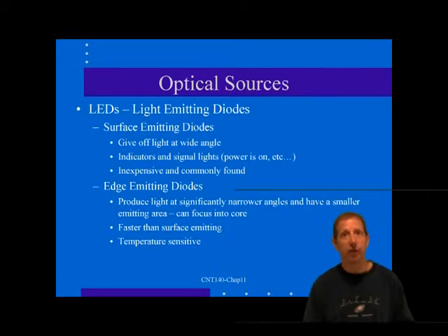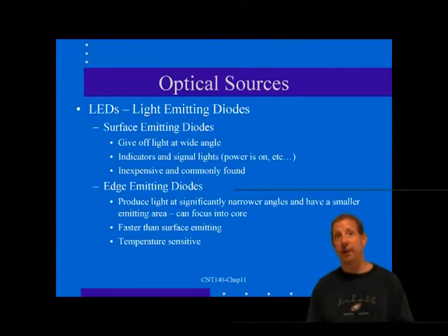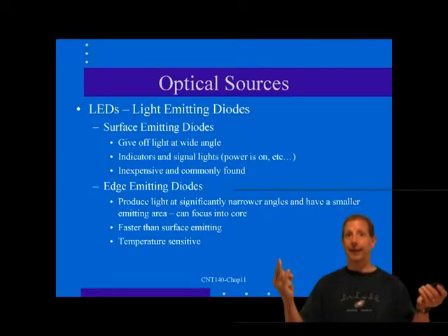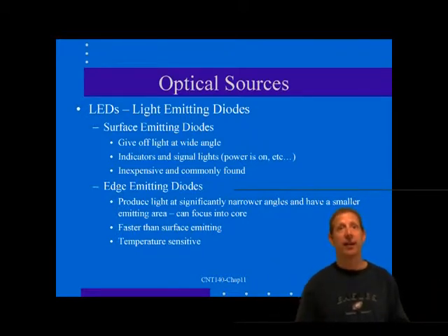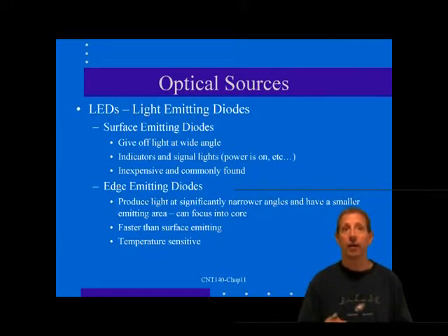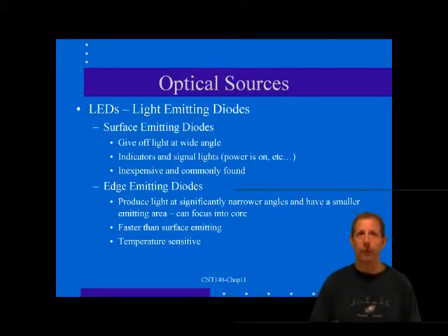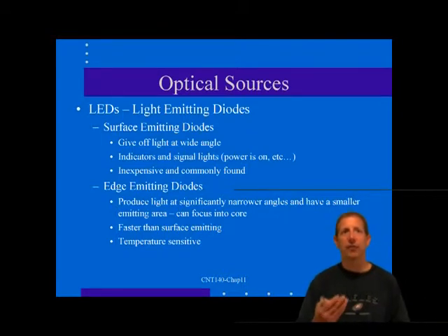However, as we just covered, much of the installed fiber in the local network is actually multi-mode fiber. Back when we were using LED sources for the lower speed technologies, such as 10BASE-FL and 100BASE-FX, we simply aimed the LED at the transmit end of a multi-mode fiber and we just let things happen. In effect, the excess light did not fill the core, it was just lost. But the light that did enter the core of the fiber propagated along the core in all modes, thus the term multi-mode. Now the method of applying the source light to the fiber is called the launch, and applying more light is needed in an overfilled launch.